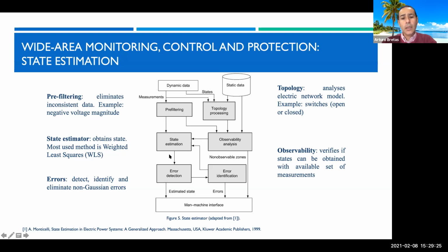Specifically on this stage here, the state estimation stage, we have several solutions, but they differ only slightly regarding the models, meaning that they're usually quasi-static models. They're taking a picture, if you will, of the grid and trying to solve that picture or that frame with a static approach. While there have been some proposals since the late 70s, early 80s of using dynamic models, such as the Kalman filter family, nowadays the great majority of utilities use quasi-static models.